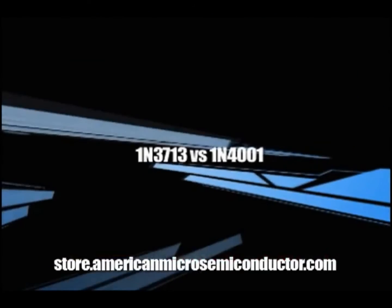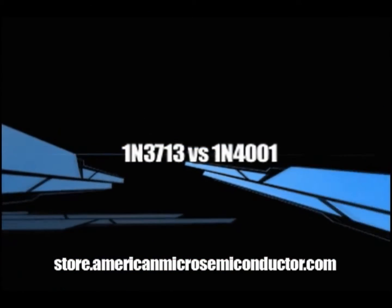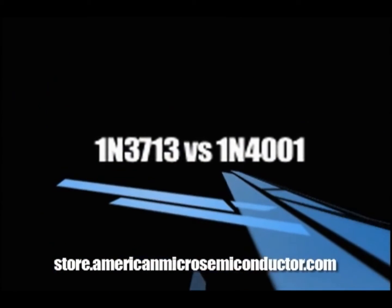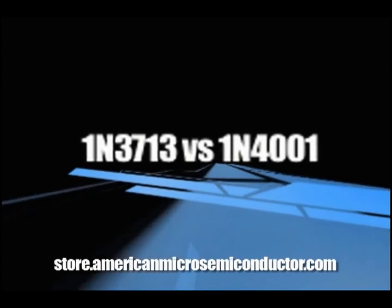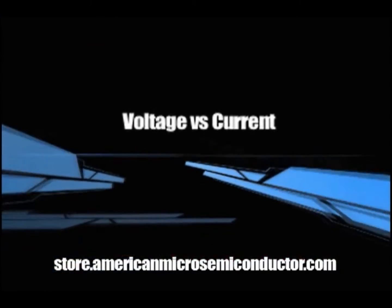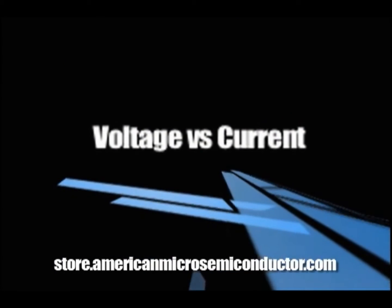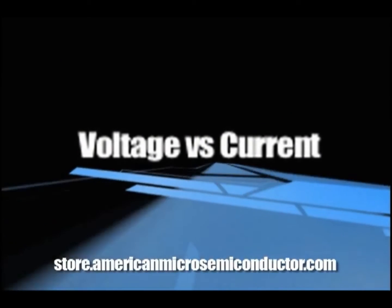In this demonstration, we're going to use a very fast switching tunnel diode, a 1N3713 tunnel diode, and compare it against the curves that are generated from a typical silicon diode. We'll be doing this on a curve tracer, and what we're particularly interested in looking at is the voltage versus current characteristics. We're going to compare a standard diode that is not fast switching versus a tunnel diode that is extremely fast switching.